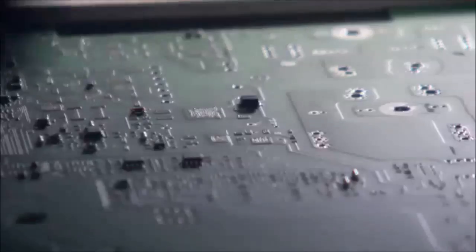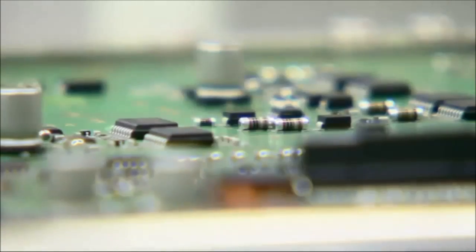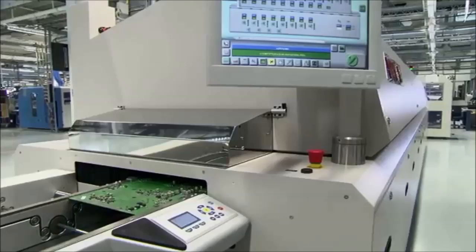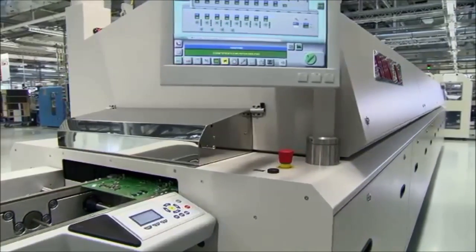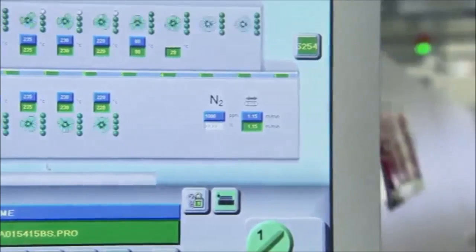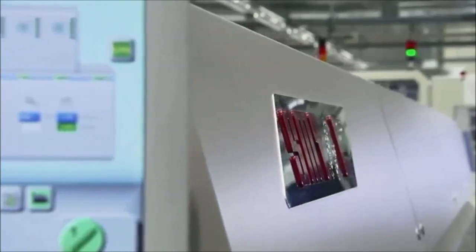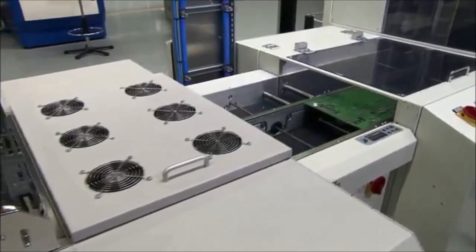Therefore, the machines operate precisely but also extremely fast. Each one of the 2 insertion heads can place up to 60 components per second. To accomplish this, they save time by carrying a supply of up to 20 components in a rotary magazine. This allows them to place several components without having to retrieve another one each time. After every component is placed, the board passes through a 23-foot-long furnace. A temperature of 500 degrees Fahrenheit causes the solder in the spreadable soldering paste to liquefy. Now, the SMD components are bonded firmly to the board.